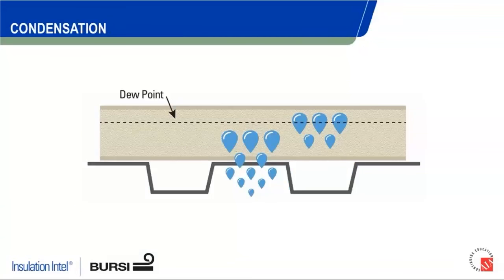So moving on to another issue with your insulation package, and that's dealing with condensation within that system. Thermal drive from inside of a building to out can cause damage to the insulation system itself and that roofing system. If condensation hits the dew point as it moves through your insulation, it will condense. It will destroy that R value or reduce that R value.